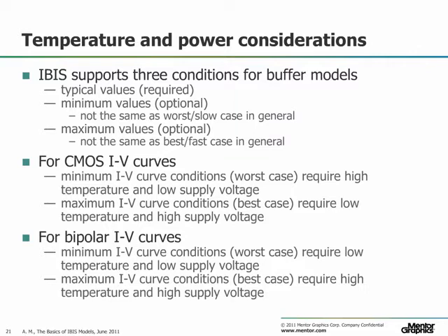Take for example the situation with the IV curves and die capacitance. The IV curve is mostly determined by the chemical composition of the silicon. The die capacitance, on the other hand, might depend mostly on the metal deposition on the silicon for the die pad and for the interconnects between the transistors.